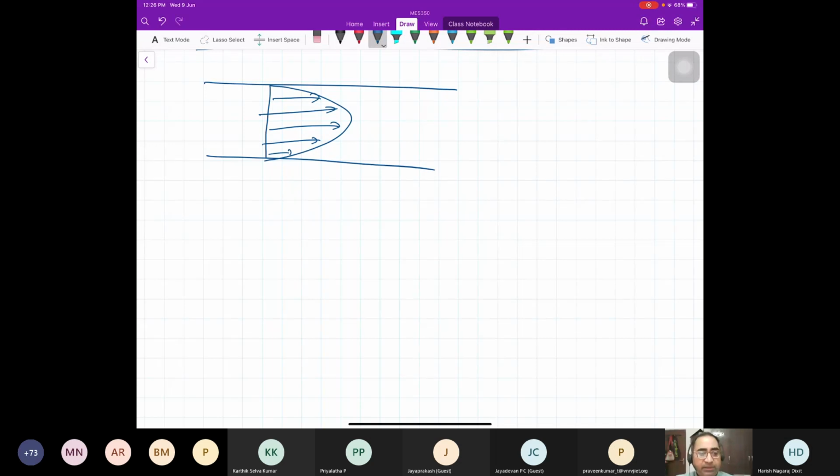If you just do a linear stability analysis of a simple pipe flow, parabolic velocity profile, you will see that the analysis concludes that it is always stable. Always. But how do I see turbulence in it? So people needed other explanations. So there's this whole range of flows between laminar and turbulent which are transition, which need not be turbulent.